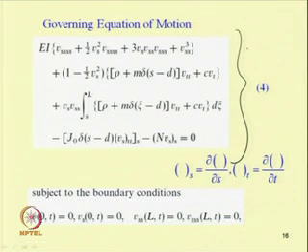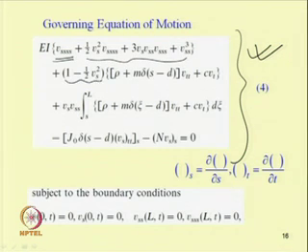As we are differentiating the bending moment twice, we will get the loading equation or the force equation. So, we have this equation of motion. We obtain the equation of motion which is written in the space and time coordinates. So, v is a function of space and time. This equation contains this del fourth v by del s fourth, which is the linear term present in the Euler-Bernoulli beam equation, and one can note these are the additional nonlinear terms present due to the term we have considered in the bending equation.